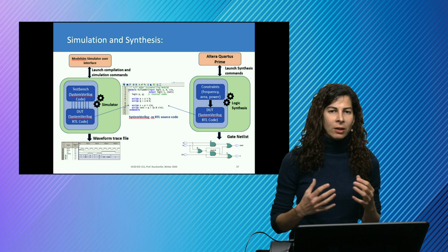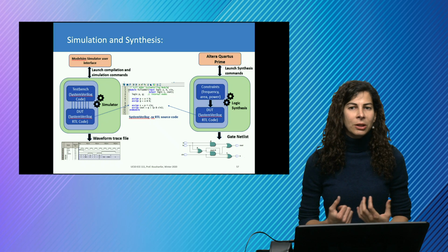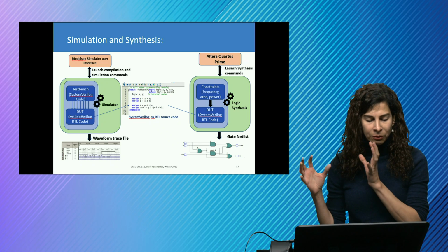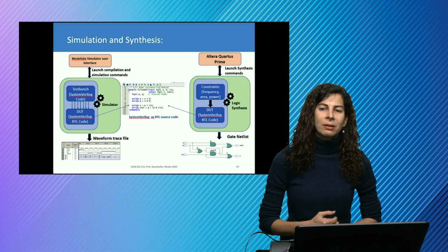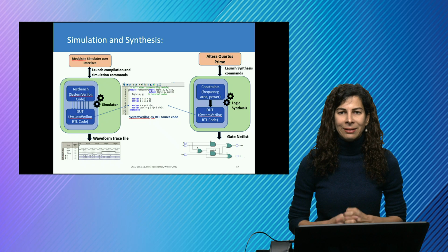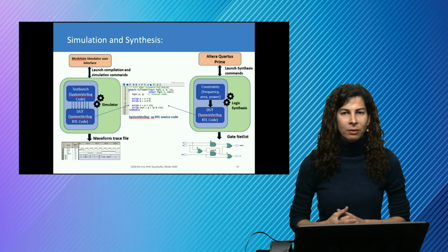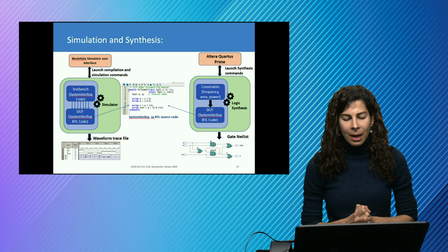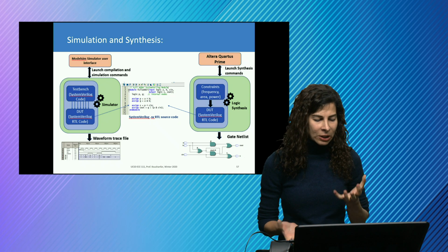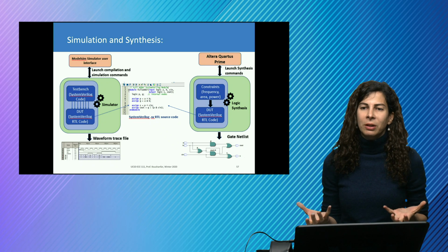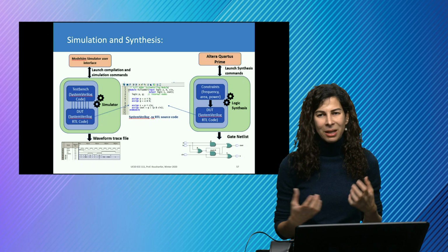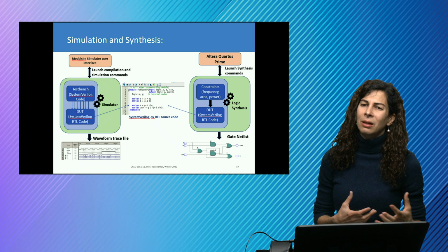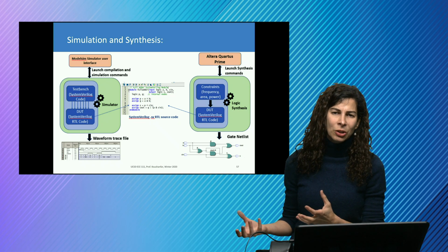After we have got this design done in simulation, we go and we synthesize it on the real piece of hardware. And the tool that we use for synthesizing into a real piece of hardware is Intel Altera Quartus Prime. These two are both essential in making designs, because we cannot make a big design before we simulate it. We cannot make a physical implementation of it.